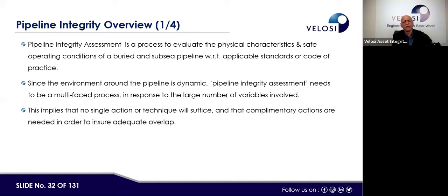Whereas in the pipeline side, mainly we transmit fluid from one end of the area to the other end. So it's only pumping for the liquid, and compression basically for the gases. And then it is one pipeline which is going kilometers and kilometers, and fluids are transmitted under the fluid head. However, as the pipeline is going from one area to another, there are pressure changes. The fluid composition will remain more or less the same, but it will have some erosion effects inside.